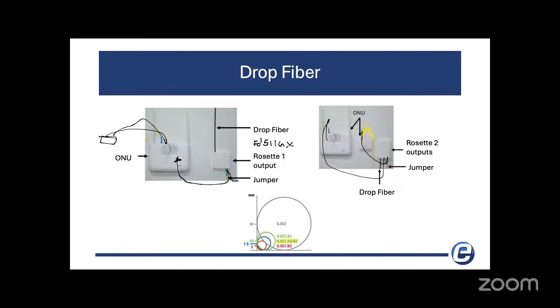Most other sellers manage this one, the A1. So what's the difference between 10 and 7.5 millimeters? Well, when you're manipulating the fiber, maybe in a turn, you turn too much and it breaks. So having better resistance is recommended for most of your installations. Maybe you know how technical people are not as careful. They want to get the job done quickly. So maybe they bend it a little more than they should and it breaks.